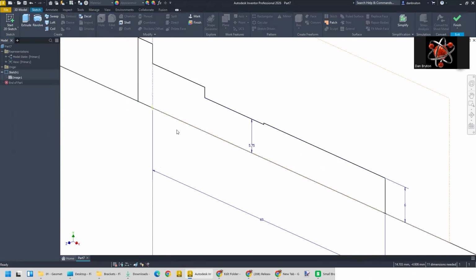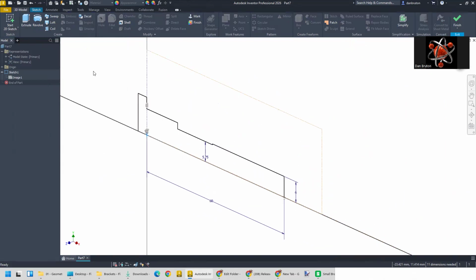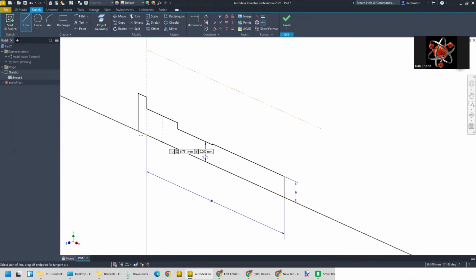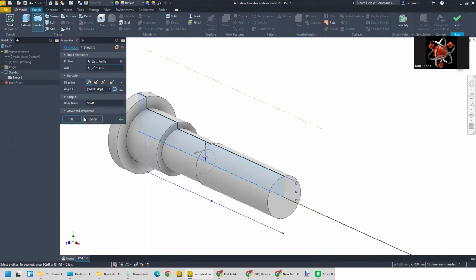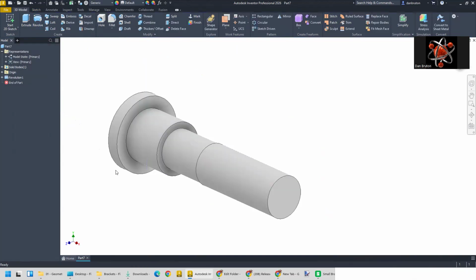So it's going to delete that. Oh, that one was projected, so that's okay. Let's try to close that shape in our sketch all the way from beginning to end. Then we'll try to revolve it. I just really like it when you can turn this into this, because if you do it the right way, you hit revolve and it knows exactly what you're doing, just like that. Okay, so this is going to be what we're going to do then. We'll just leave it just like that. You saw the process that I went through to pull that off. All right, let's put some threads on here. Let's put like a little chamfer on here and on here.